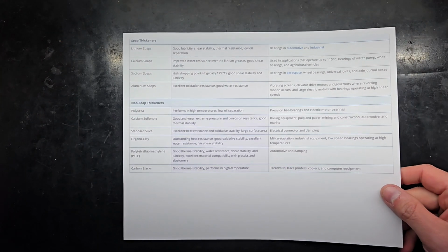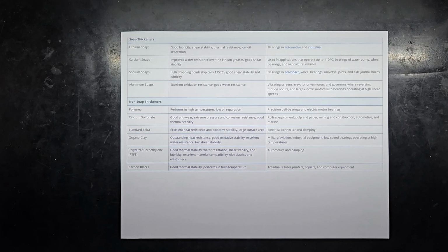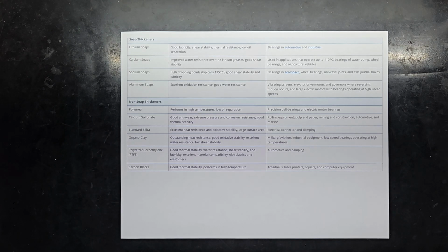For a lithium grease, so lithium greases are the prominent greases here in the United States, you would react a 12-hydroxystearic acid plus a lithium hydroxide monohydrate, so that's your base, and then the resultant is a lithium 12-hydroxystearate, which is the grease thickener, plus water.